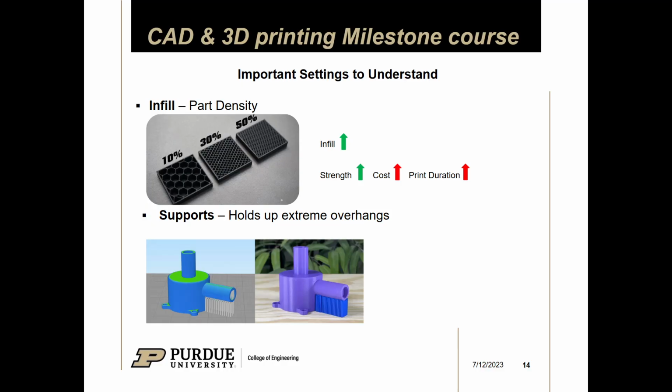So you can increase or decrease that to save time or make it stronger. Again, I typically recommend perimeters before infill, but having a good balance is good. The standard is typically like 3 perimeters, 15 or 20% infill. But when I want to print stronger parts, I can go like 4 or 5 perimeters at like 25% infill.